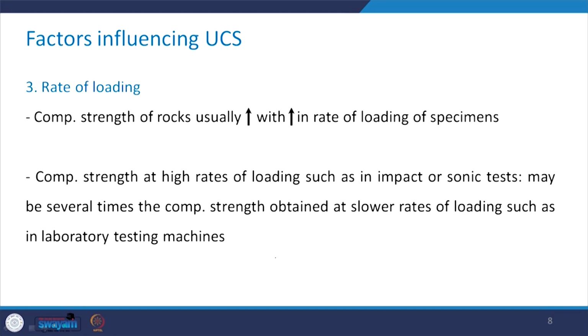Then the rate of loading. It has been seen that the compressive strength of rock usually increases with an increase in the rate of loading of the specimen. For example, at high rates of loading, such as impact or sonic tests, and this is very interesting, when you conduct the test at such high rates of loading, the strength can be several times higher than the compressive strength test which you conduct at a slower rate of loading in laboratory testing machines.